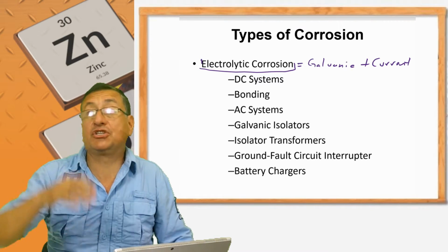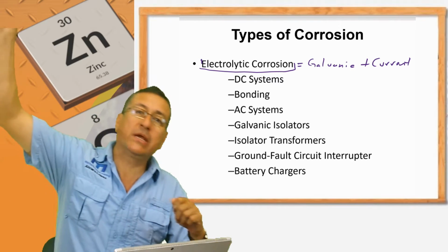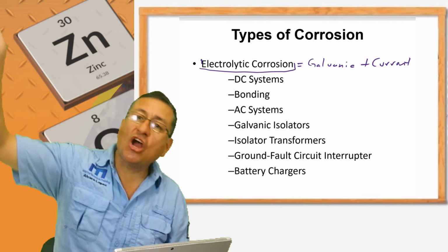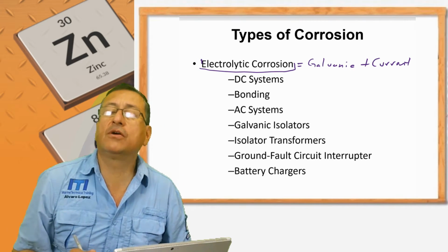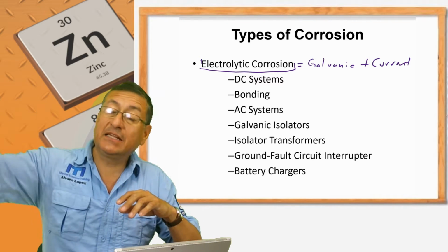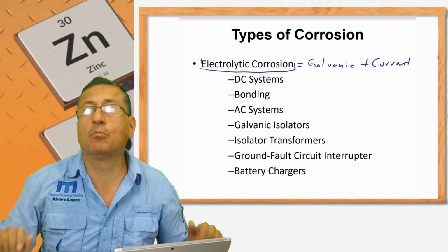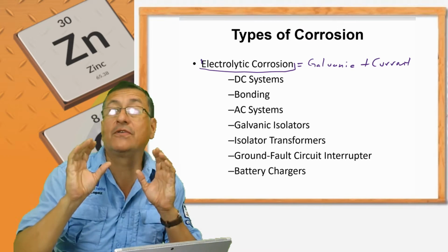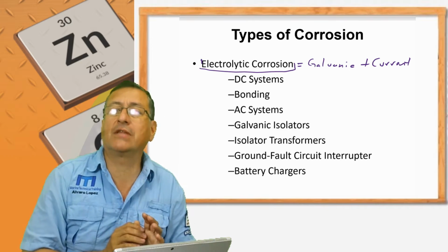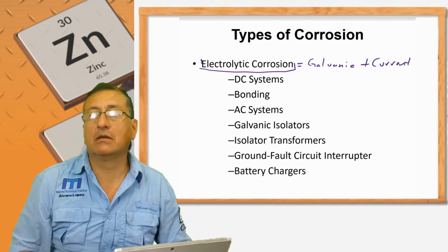If I have a short because the hotline of one AC cable touches the metal, that current is drained immediately and finished. But you don't have a constant flow of AC current, because when you have a short, the hotline touches the ground, immediately the current is drained, but the breaker is out and no more flow. For a couple of seconds, milliseconds, you have a big current flowing, but it's for a short period of time. Constantly, you don't have AC current passing through the block of the engine.